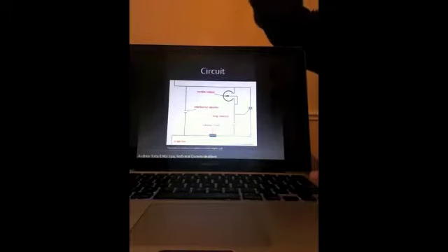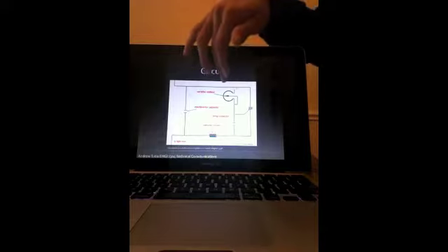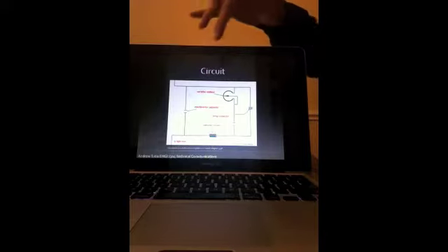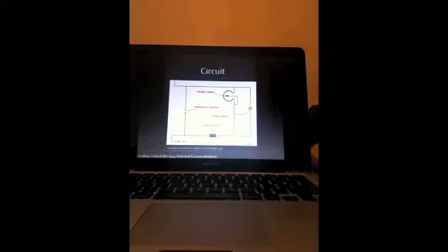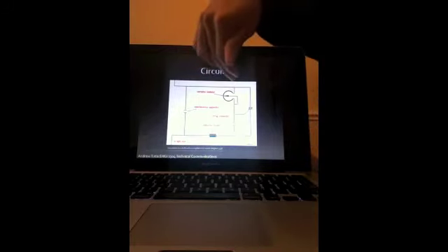Here is a picture of the circuit, and here is the variable resistor, the triac, and the firing capacitor. The variable resistor you see here is a circular resistive material. Whenever you turn the knob to a clockwise position, let's say you're turning it down here, the current will have to go through less of the resistive material before being reconnected with the circuit.